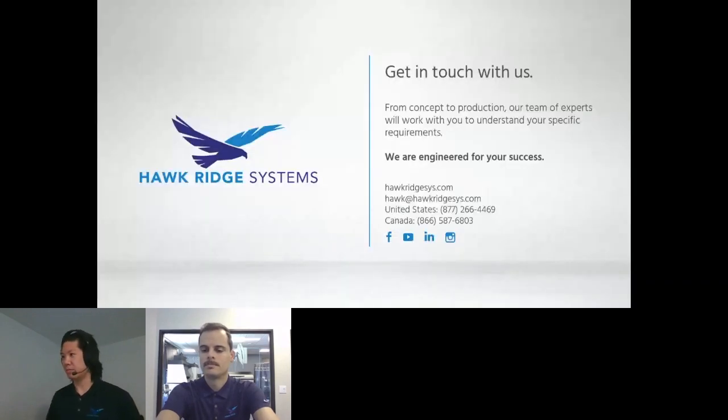All right, got some questions here. Start at the top. I think that's earliest. Ross is asking, are these solving techniques available in SOLIDWORKS or only Simulia? Some of the more basic techniques, just the simple implicit nonlinear analysis, that is available in SOLIDWORKS. Some of the more advanced techniques, explicit solving, ALE, CEL, those are only available with the Simulia tools.